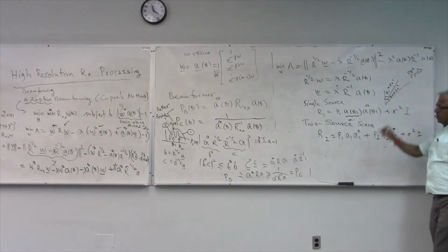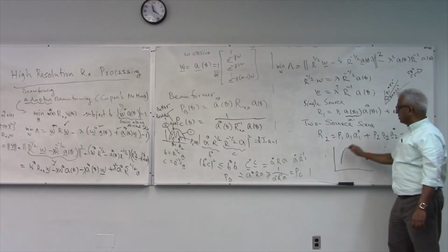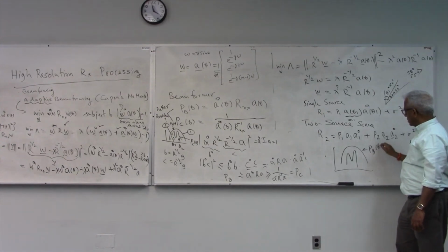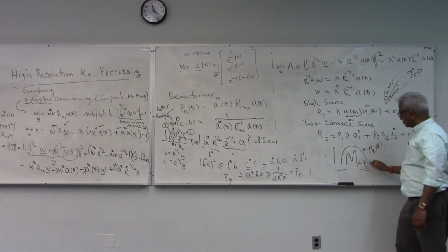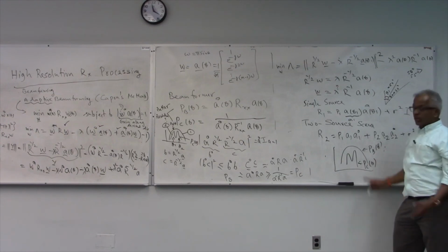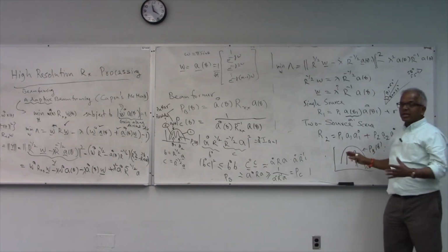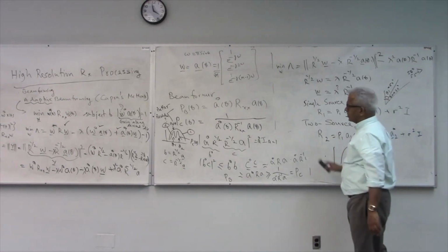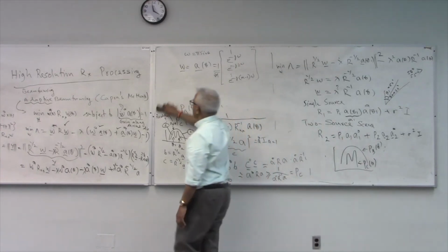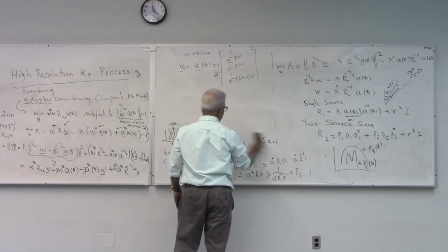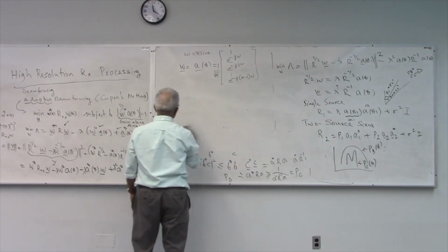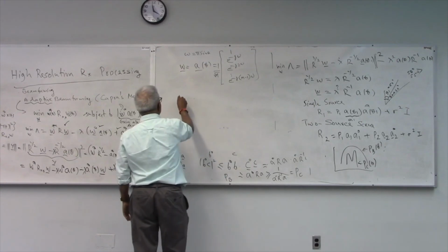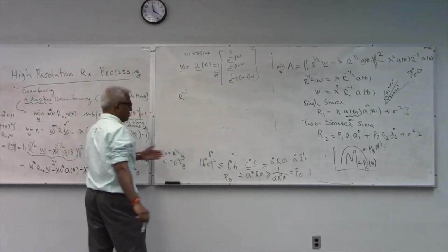Most likely the beamformer, so what I want you to do is plot the beamformer and the Capon output. You can also do this by hand and see the resolution. So I already did this one for you, right? So PC would be what? PC, you have to invert that matrix, right? So the rank 1 inversion is easy, right? So you have to look into some books and see how to find out R1 inverse. Remember, you need R1 inverse here, right?